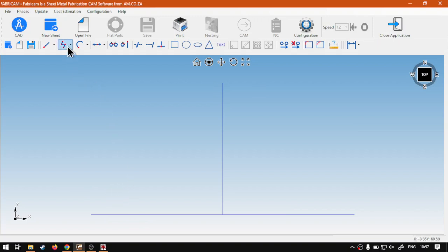Now we're going to head to our Polyline tool, the several points. Select that, and then find our hotspots, so hover on the corners. I'm going to select this one, then the next one, and then the last one. There you go, and then make sure you right click out of it, otherwise it will want to create more polylines. And that's how I went about making it.